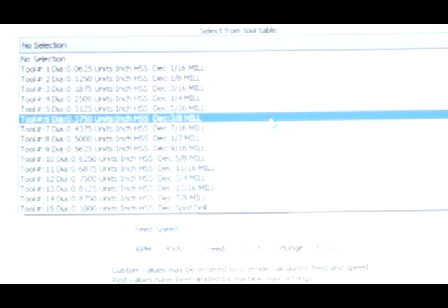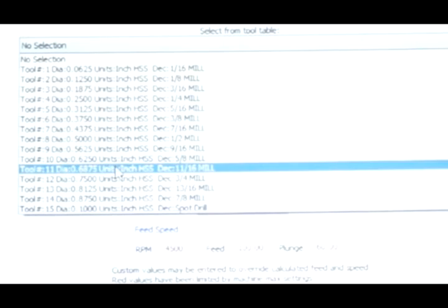But I can look down here and I say, all right, I'm going to do this job with a 1/2-inch mill. It populates this input line with everything you need to know. Our tool table carries a couple of values in it, the type of tool and the number of flutes and all that stuff. There's also this ramp angle. We are very good now about ramping down into a job. And you can specify a ramp angle. And like here, I'm saying 5 degrees.